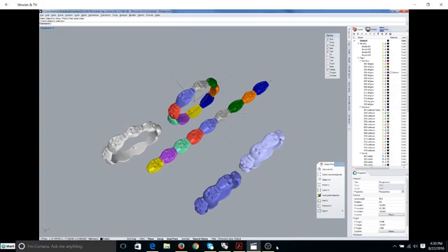That's going to be a combination of the software and how it runs, and also your memory and your system. I think the one I have is 24 gig, so I don't have too many problems. Rhino will have a limitation on polys. In ZBrush, I've seen 20 million polygon models. It doesn't operate the same way or use the same graphics that Rhino uses.